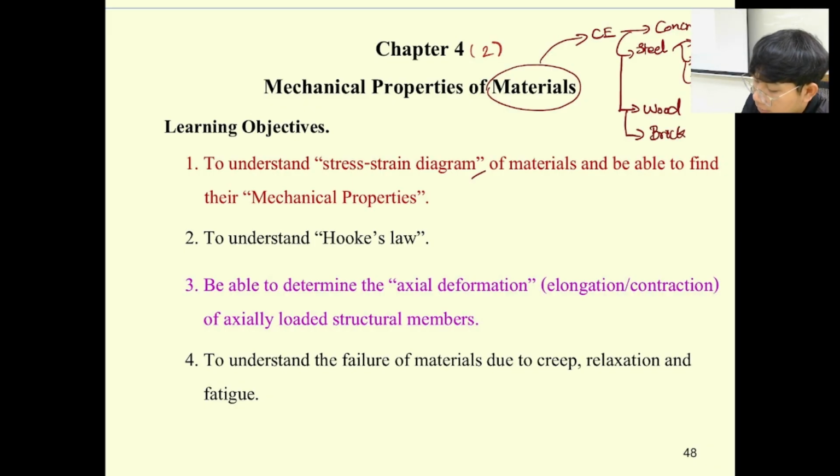I think you have done the brick test at F4 already, right? Last week, is it? Okay, so in the brick, you need to test what we call every angle. For example, flat wise, angle wise, and then in the vertical direction, in order to see the capacity that it can resist.